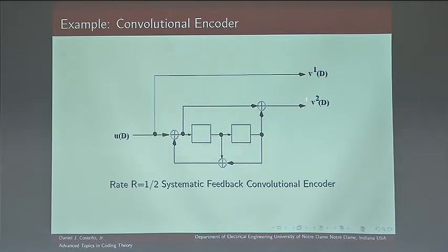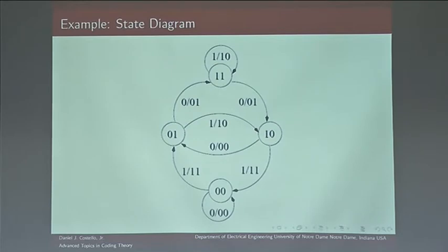So we're going to have 0, 1 coming out. And the 1 that was here is going to shift down here, and the 1 that gets fed back is going to shift over here. So we should get 0, 1, and the next state should be 1, 1. And that's what we do have. We get a 0 input, we have 0, 1 out, and the next state is 1, 1. And again, I'm thinking of this as 1, 0.